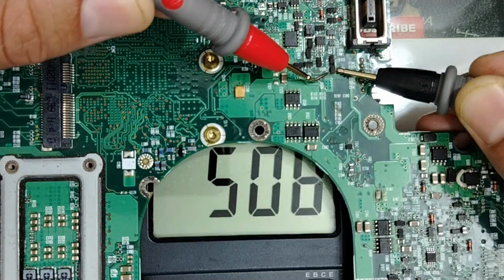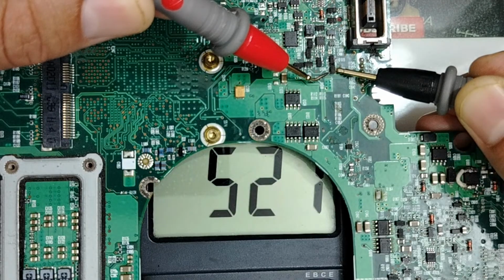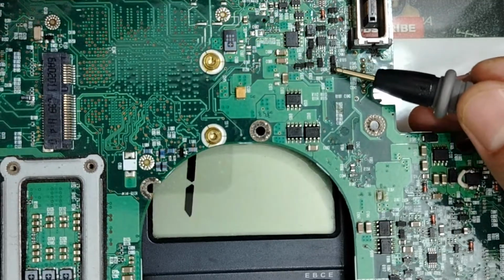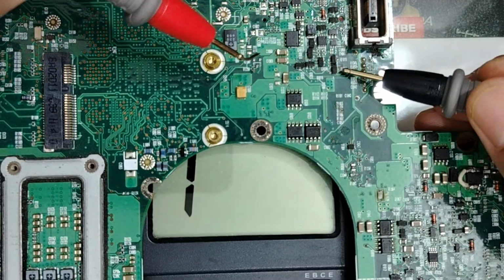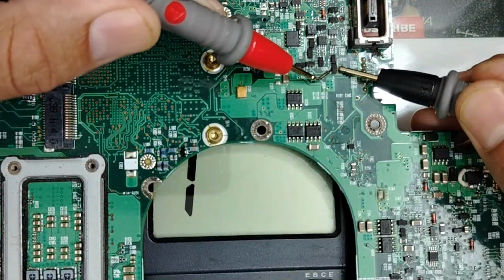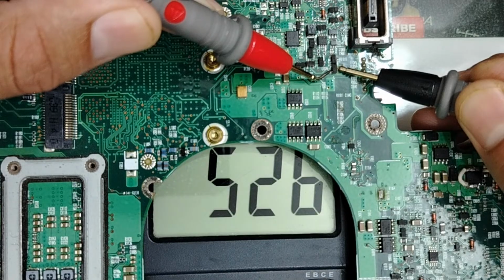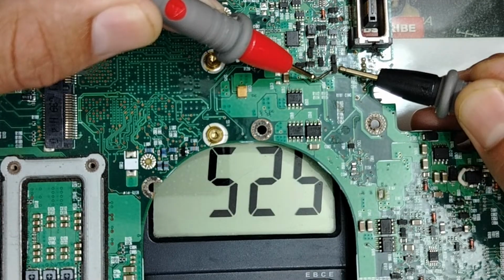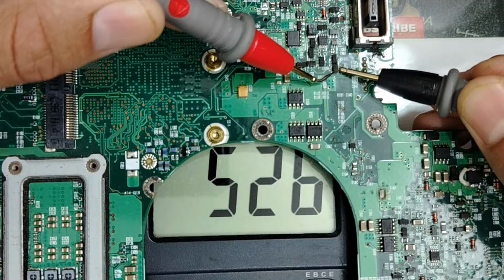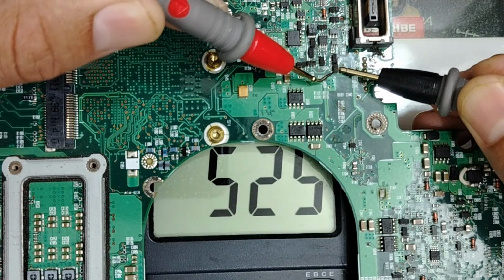the exact reading. Okay, my friend, this is another test, and basically this is the most reliable test for MOSFETs. So for MOSFETs, my friend, you can test it by putting the black probe here in the drain and the red probe in the source, you get a reading. Good, we get 500. This is good. But if you want to double check, by checking the MOSFET like this, my friend, 80% the MOSFET is good.